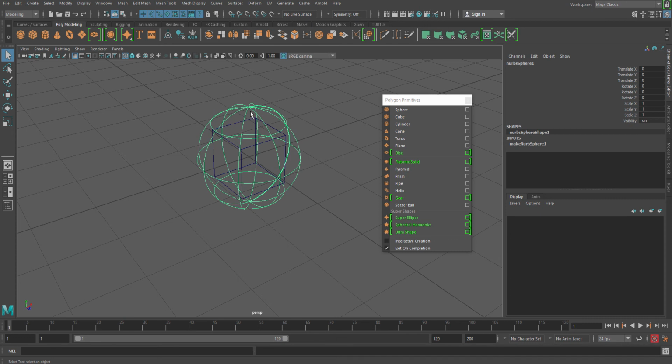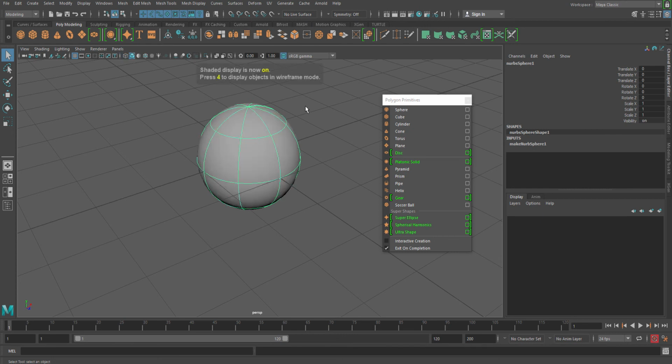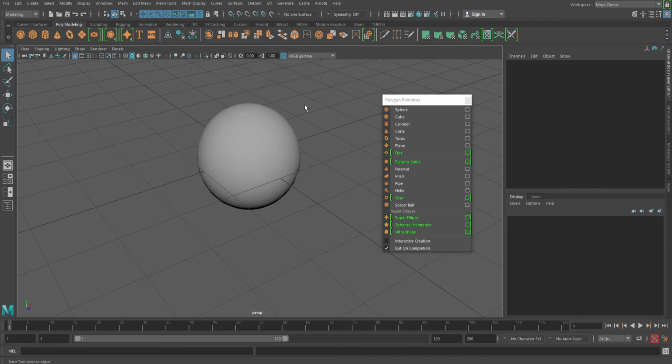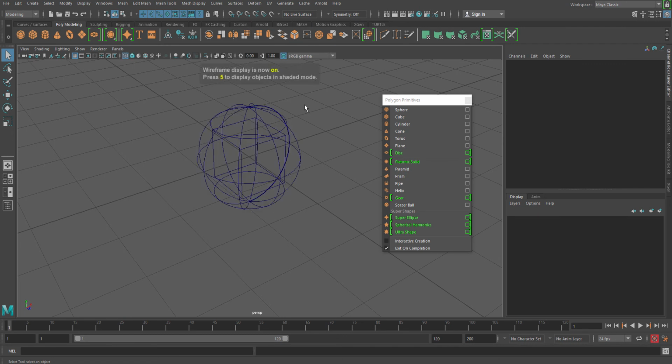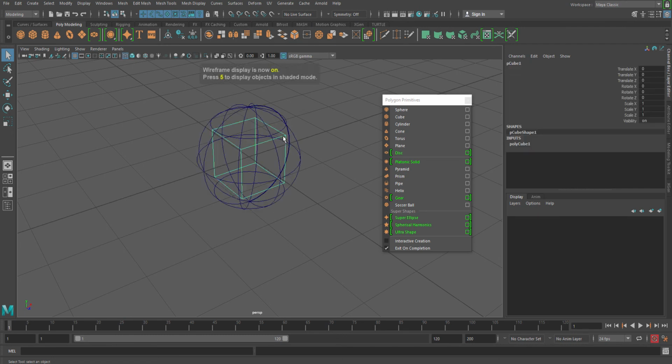So first of all, let's select the objects and try to move them, because my objects are getting hidden and I cannot see them. How can we move my objects? First I have to select it, and for that I have to go to the wireframe view. I click on the object, and then go to my move tool from here. Immediately you can see the three-dimensional gizmo is activated, and I want to move it along the x-axis.